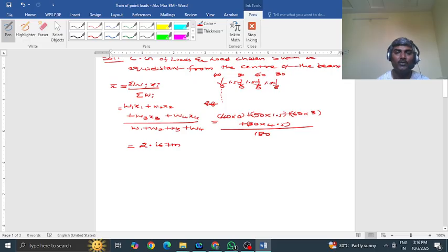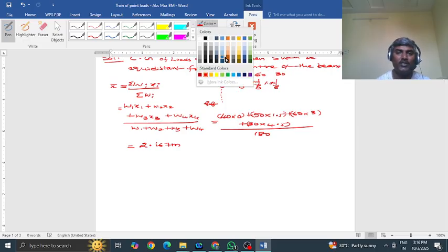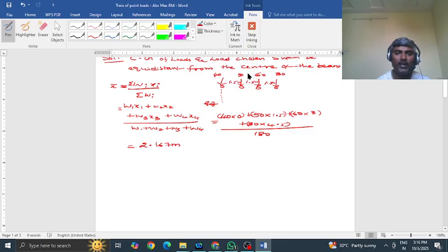Let us locate that CG here so that we have an idea. It is 1.5 meters till this load and 3 meters till this one, so it is in between, and close to the 50 kilonewton load. Represent it by a dash-dot line. This is the X bar distance, and this is the CG of all the loads.